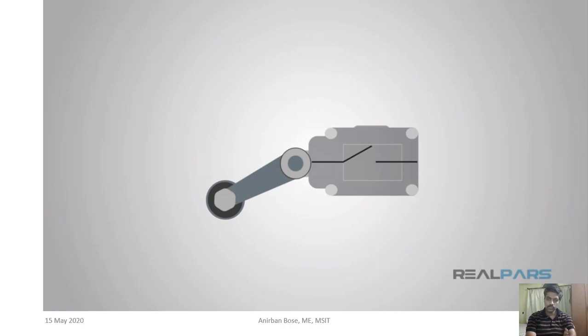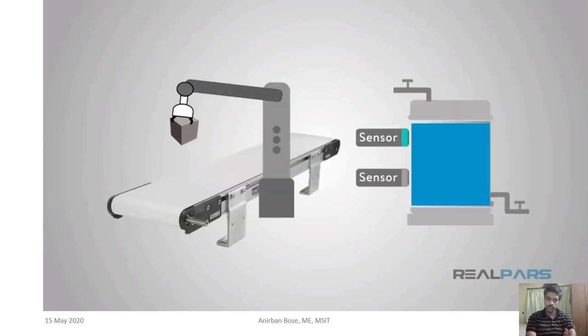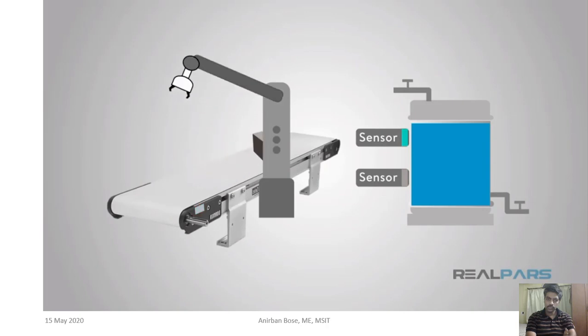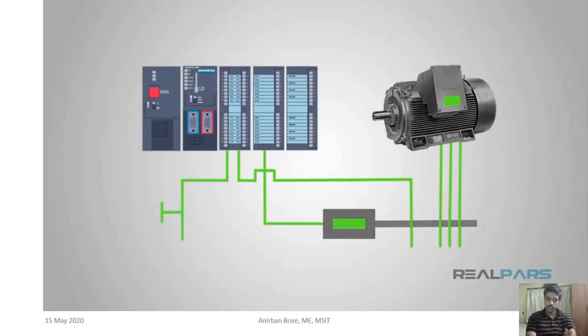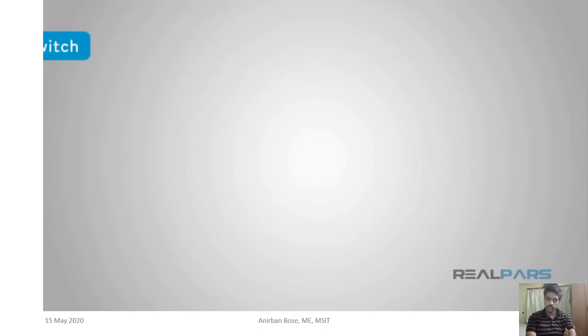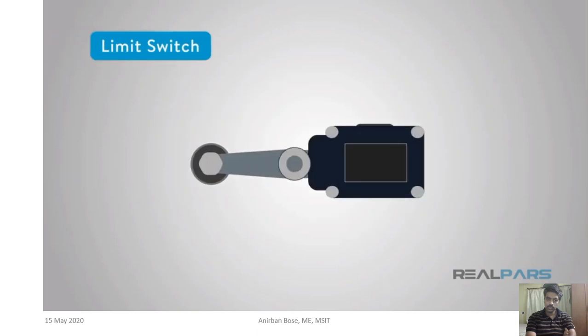We use these sorts of sensors for anything that we divide into two states: on and off, true and false, is and isn't. For example, in position, full, empty, power on, and running. Let's look at a few examples of these kinds of sensors. First, as mentioned before, mechanical switches of various kinds are still around.